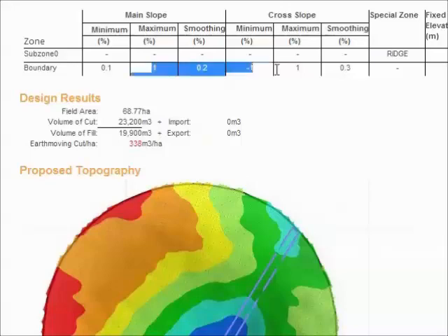If we removed all of these constraints here and just kept our minimum constraint of 0.1%, we can actually halve this earthworks. And we wouldn't recommend it for a couple of reasons. We think the smoothing and the maximum slopes improve irrigation and rainfall infiltration uniformity, and it allows the earth moving machinery to follow this design more correctly, and obviously for machinery access such as harvesting and planting, you'd like a smooth surface to work with.